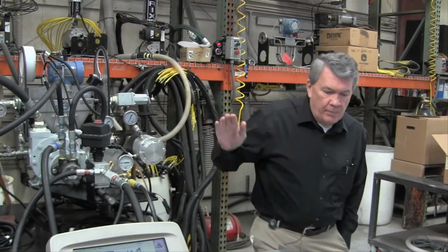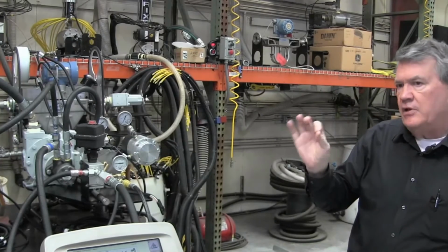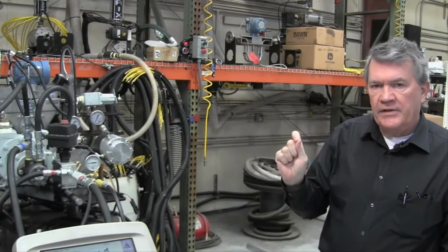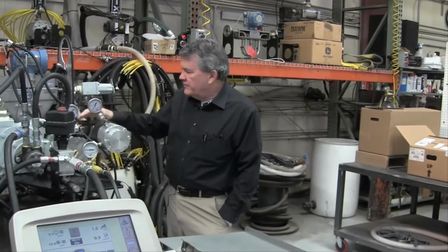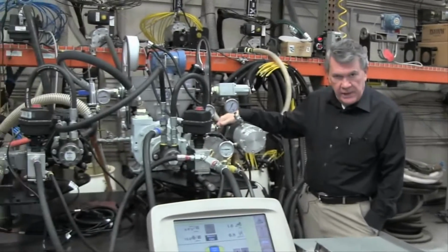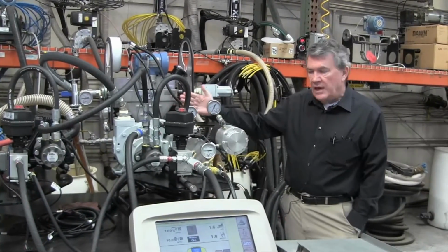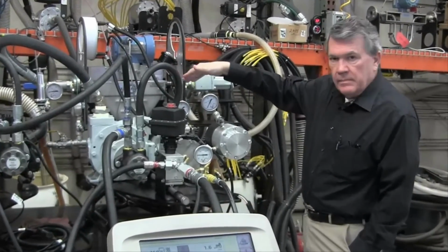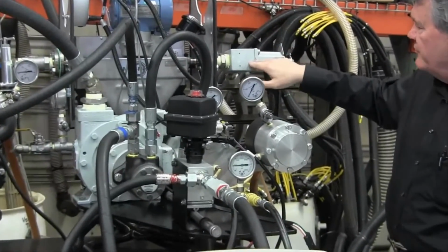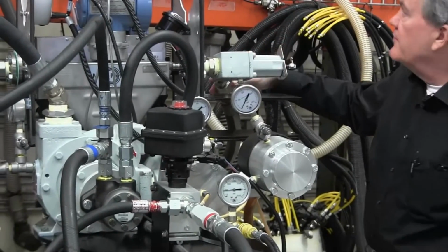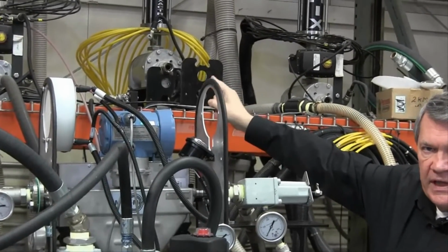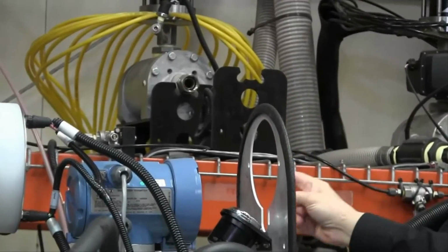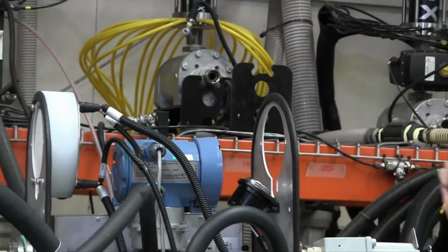Once again I want to point out this is a presentation. It's just basically to get the nomenclature down, and we'll explain a little bit more about the details. Just to reiterate, this is the phase shifter. This keeps the ammonia as a liquid going into the sliding vane, out of the sliding vane, past the mass meter, past the discharge valve, and from the discharge valve the flow goes up here to the liquid manifolds, and that maintains the ammonia as a liquid. Then those lines circulate on out, they go to the injection point, and there's a terminal orifice at the injection point.